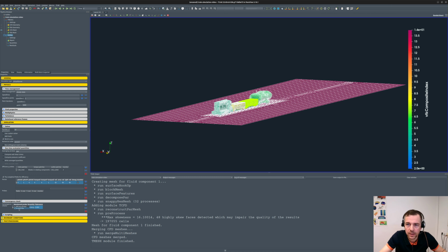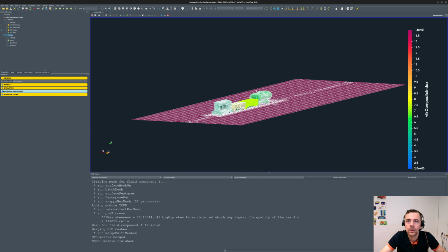I will say okay, there will be a force probe and the average drag coefficient, and when it reaches a tolerance of 0.01, then the simulation is allowed to stop and give me the results because it's accurate at the moment. It's accurate enough for this kind of simulation.